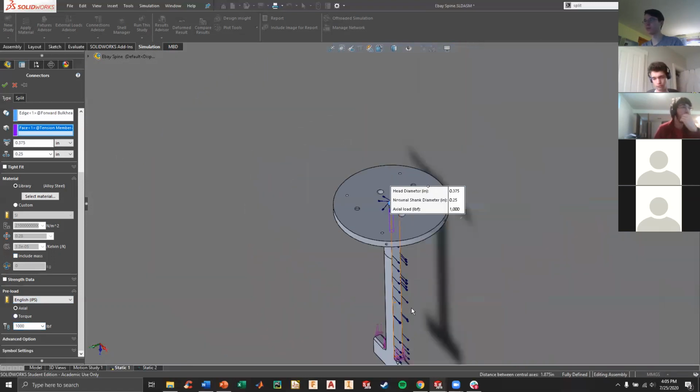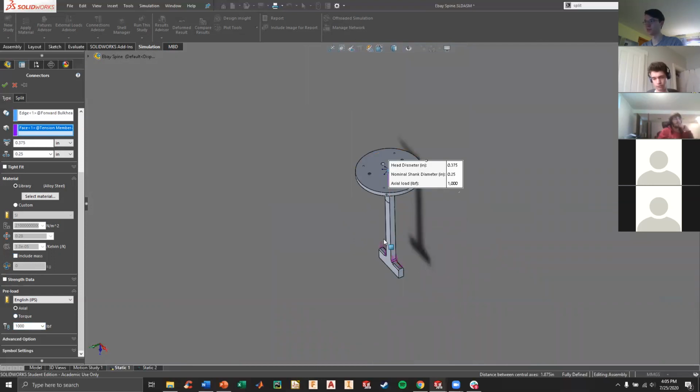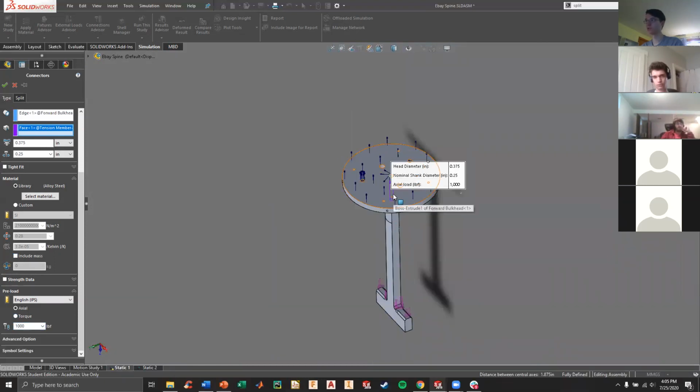This is a pretty simple model to analyze because the force acts directly opposed to a single bolt. So really you just want to make sure that the preload is more than the tensile forces that your bolt will have to be holding against, because if your preload is less than the forces that you're pulling the parts apart with, then your bolt can just come loose. That's an area where vibrations will start to unscrew the bolt super quick.